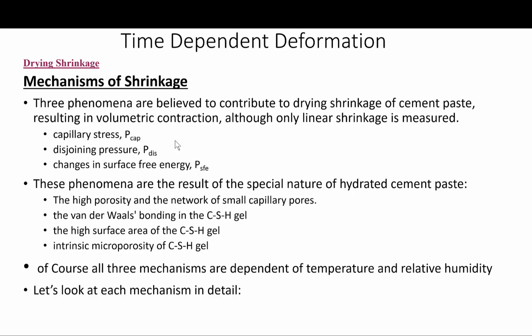These phenomena result from the special nature of the hydrated cement paste. Basically, it's high porosity with a network of small capillary pores. And also the extensive van der Waals bonding in the calcium silicate hydrate gel, the high surface area, and the intrinsic microporosity of the calcium silicate hydrate.